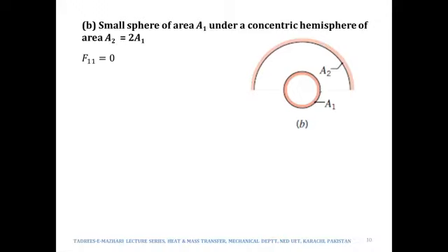So the radiation leaving 1 will be going in this direction, for example, and it will not get bent back onto itself. Therefore F11 would be 0. However, if the outer portion of 1 had been shaded, it would have meant that we need to consider the radiation from the inner surface of 1, and in that case F11 wouldn't have been 0.